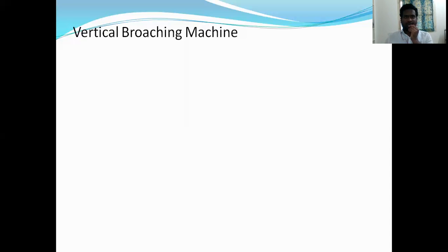And after that, the broach pilot. The broach pilot holds the cutting tool, that may be a pushed or pulled cutting tool. That cutting tool does the manufacturing process. The cutting tool removes material from the surface of the workpiece. So the broach pilot holds the cutting tool, and those are the components of the horizontal broaching machine.